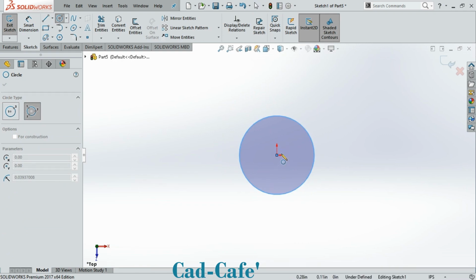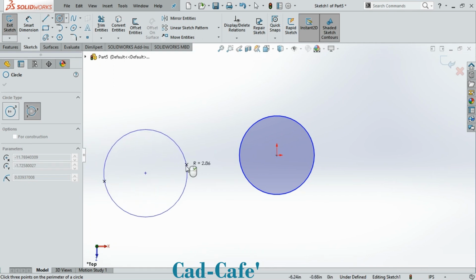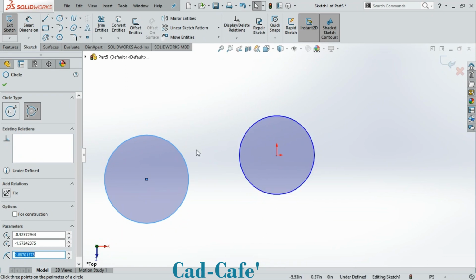You notice that this other one was drawn inside out. You start from the inside, you pick a point, and then you extend your radius outside, you click on it, and your circle is formed. But for the perimeter circle, you start from the outside. You select a point outside, another point, and then another point. Voila, your circle is formed.